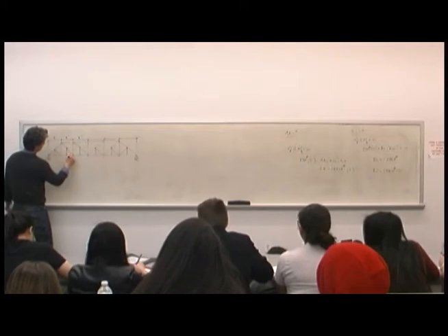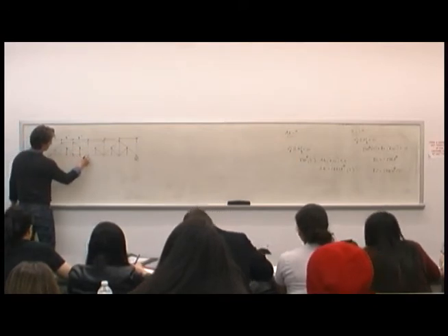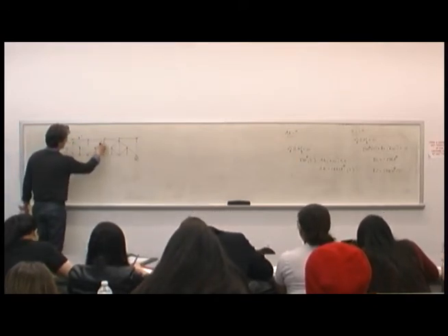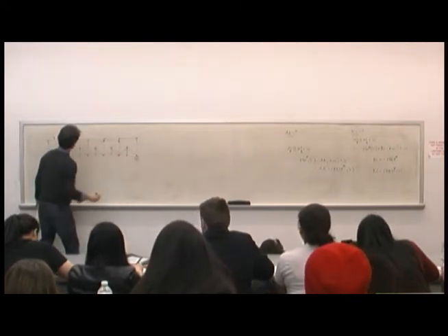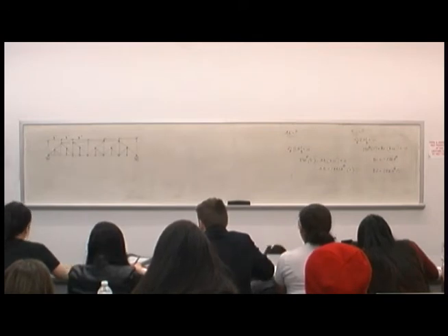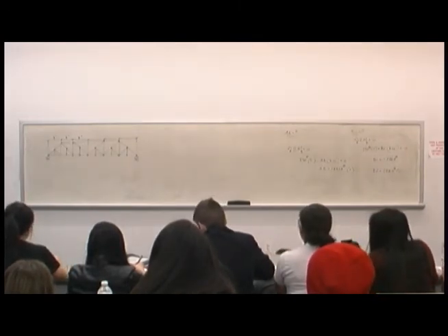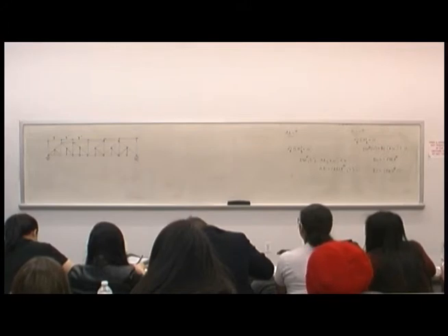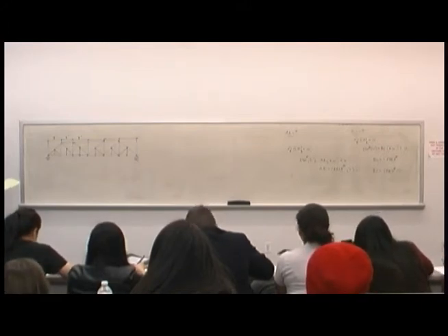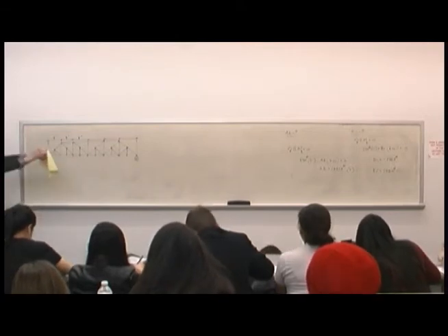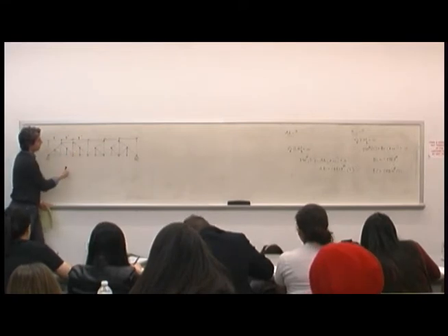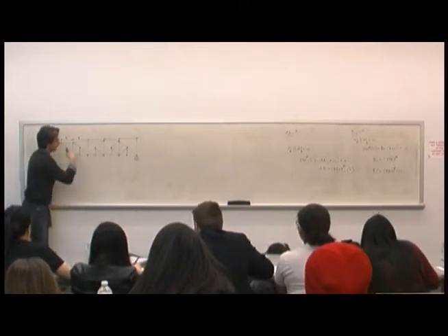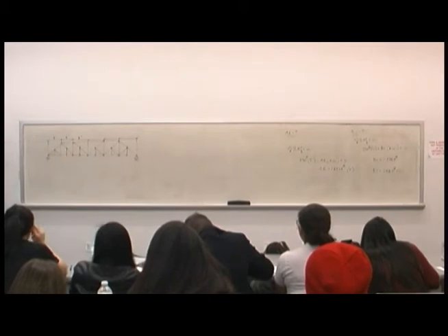So I've got this truss system. This particular configuration is actually a known truss called a Baltimore truss. You can find a lot of different bridges that may have this configuration, and the small little links help the bracing of the long diagonals. It cuts down the brace length.